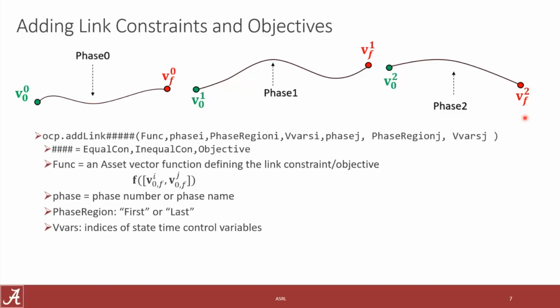Phases are great for something where you have some level of control, whether that be a problem formulated with a control vector where you're trying to optimize the pointing of an engine or a solar sail, or even a problem where I'm trying to find the initial conditions of a 3-body periodic orbit. I know this is constrained: I want it to start at the XZ plane of the CR3BP, and I want my X value to be this, but I'm going to allow the problem to vary my other initial condition states to create periodicity.